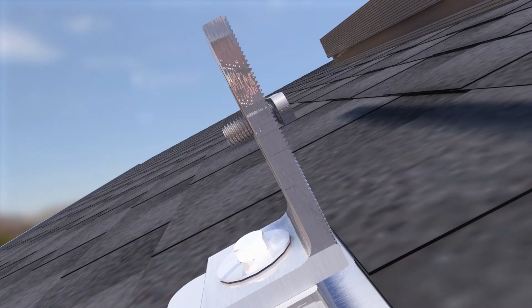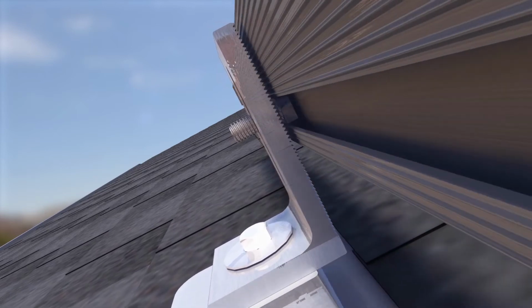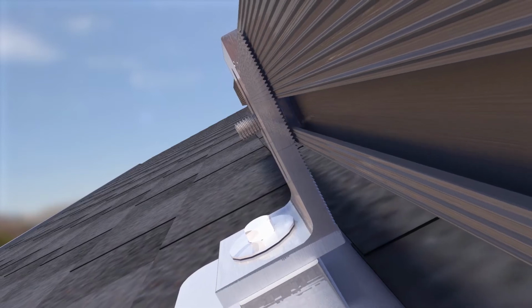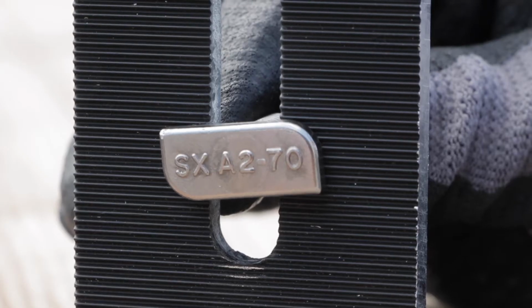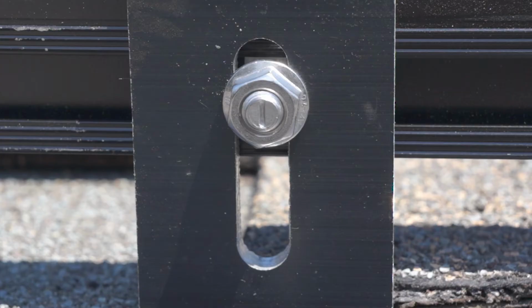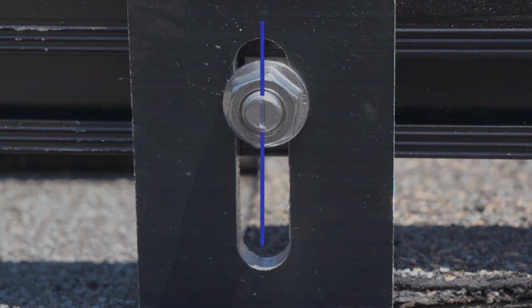To attach the QRail to the L-foot, insert the T-shaped head of the bolt into the channel on the side of the rail, with the head aligned horizontally so that it can easily enter into the channel. The T-bolt is fully engaged when the head of the bolt is rotated to a vertical position. The imprinted line at the base of the bolt indicates the exact position of the bolt's head, so it's easy to line up even when you cannot see the bolt head behind the L-foot.